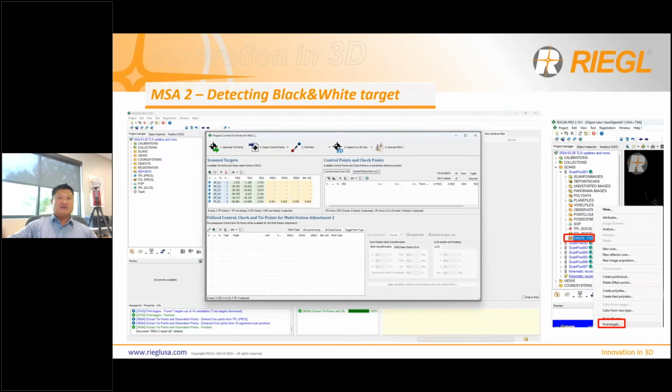So it's advantageous to scan a cylindrical target at least 2 times, especially when you're doing road projects or outdoor environments where that rod has the potential to move, right? That way we can detect the deltas between the rod from both setups. In other words, we can detect if the rod's level or not if you scan it twice.